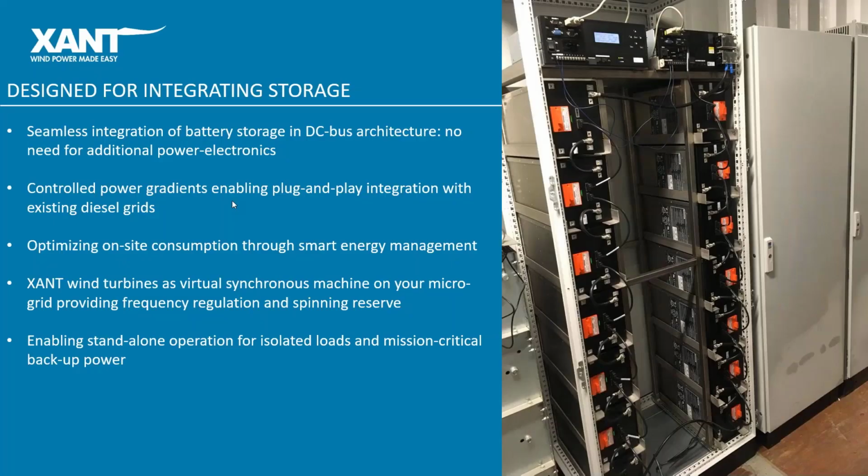One important aspect, and we've mentioned it, is the role of storage as an enabler of increasing the renewables in these hybrid power systems. We've come up with an integrated storage part where, as we have a full power converter, we can easily integrate modules of about 50 kilowatt hours into our turbine. And this opens up a whole wide variety of applications. You could still be just delivering power to the grid, to the microgrid, but you can smoothen that power, which allows for an easier integration.